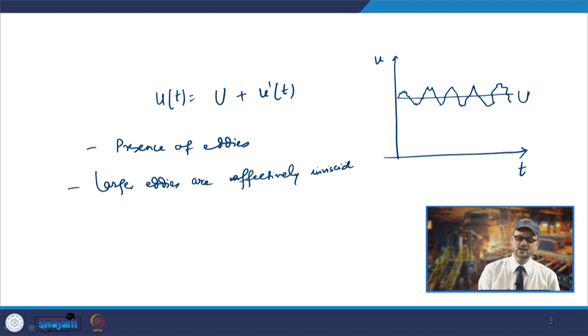Now, in those cases your angular momentum is conserved. During vortex stretching, the angular momentum is said to be conserved. That will lead the rotation rate to further increase, and the radius of the cross section will decrease.